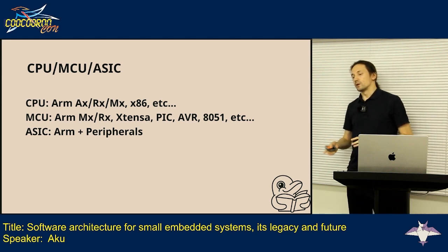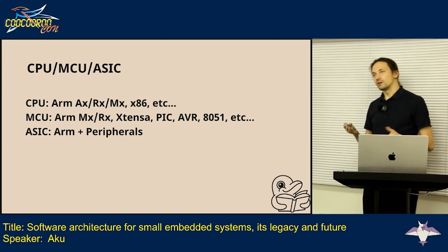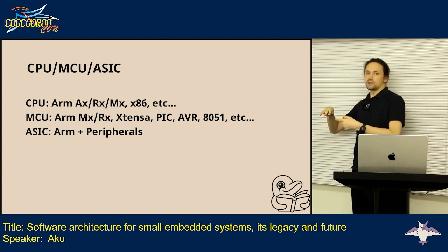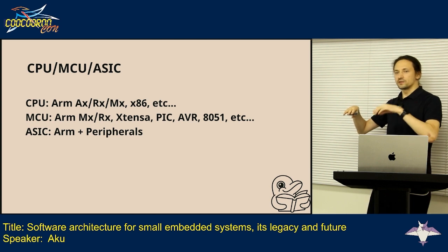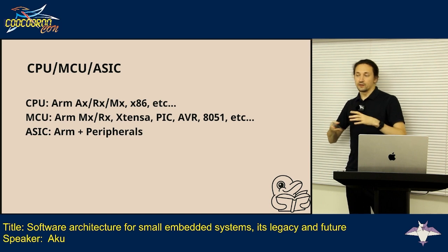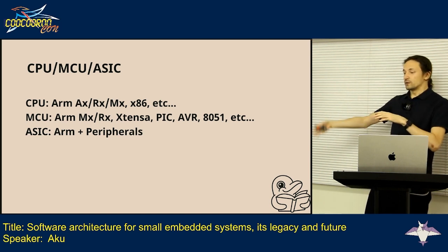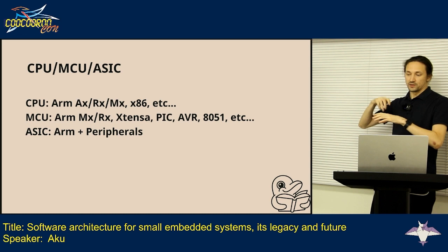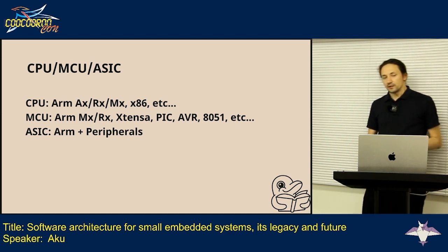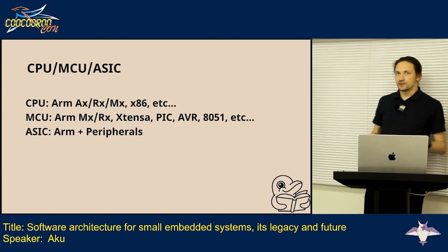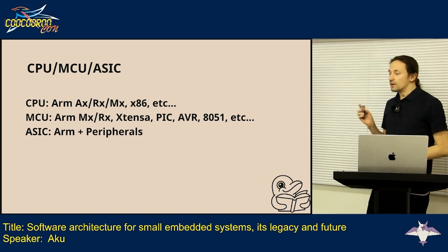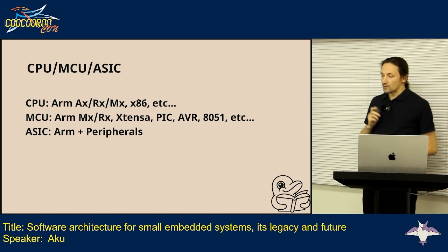And in some cases, switches usually perform tasks on L2, but we would like to perform some L3 tasks on the switch itself. Without building specialized blocks to handle L3 tasks, we can just grab a packet from L2, process it, and then put it back into the fabric. And that's what ASICs usually do. Not only that, but a huge amount of different things, like radio, some really specialized ASICs exist for it. And all of them are actually embedded.